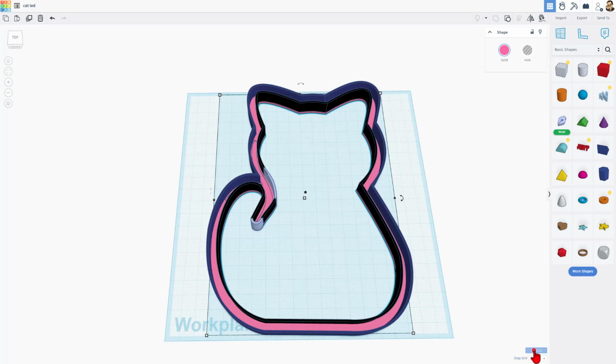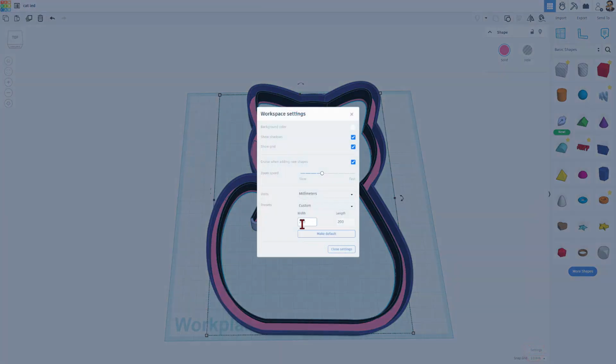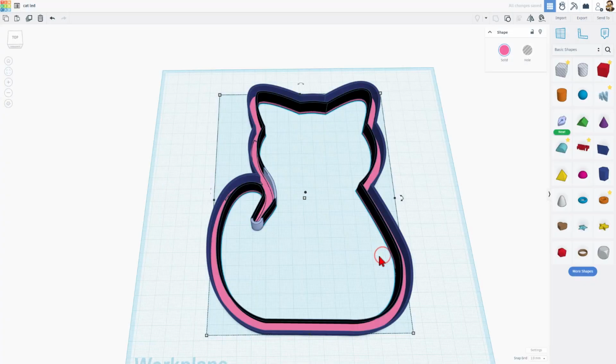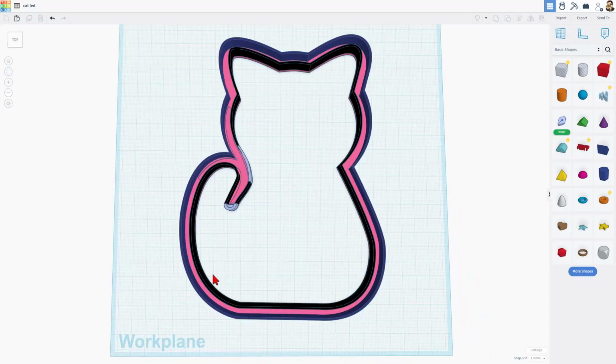I'm also going to make the world larger because my printer can handle a 250 by 250 bed. So I'm going to change these quickly to 250, and I'm going to press enter. Click out here to bring that to life. And now I want to cut in a hole for the wire. I'm going to simply bring out a cube. I'm going to keep it 20 millimeters across, and I'm going to make it 5.5 millimeters thick because our LED channel was 6 millimeters wide.